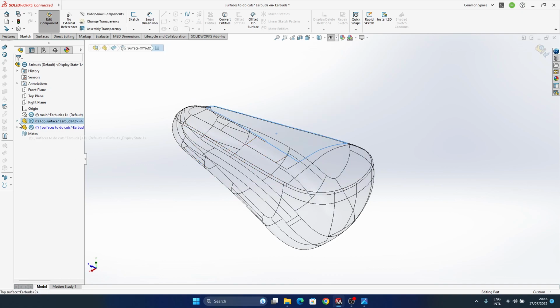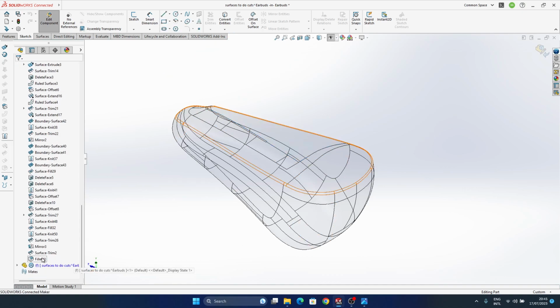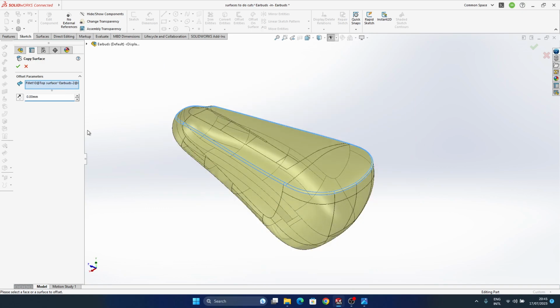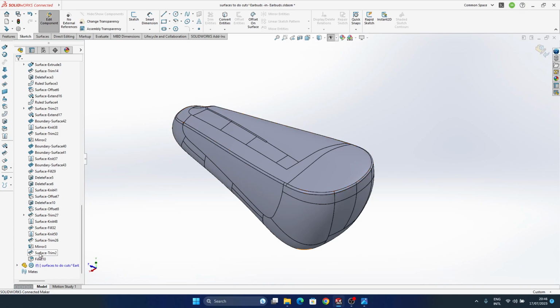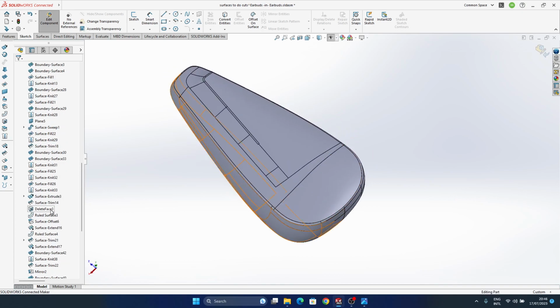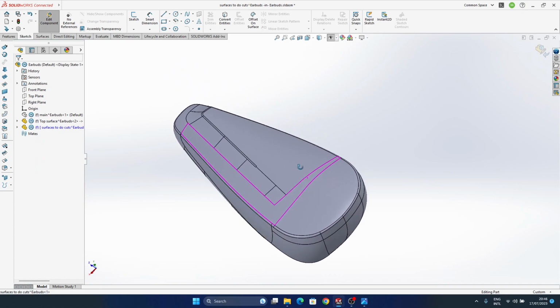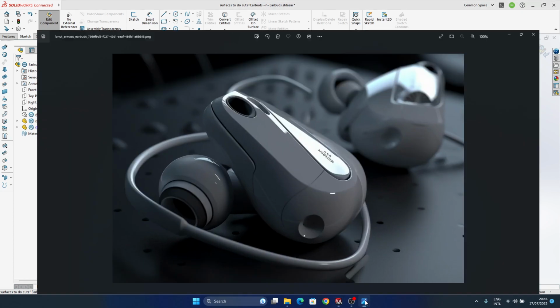I'm reluctant to select surfaces because by having surfaces, it will always depend on the selections that you make. So if the model changes, then you have to go back and modify your selections again. But getting the whole surface as a copy, then you will not struggle with that anymore. Okay, so that's one thing. So we created that. Let's look at the model in here.